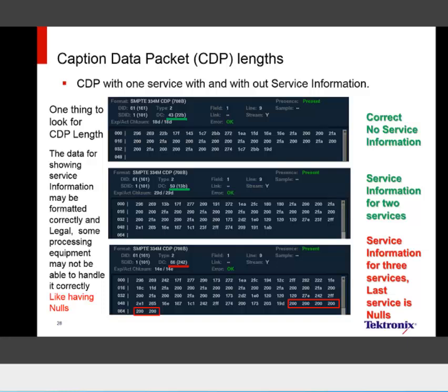This actually made a network start having issues. Whenever a scene change came up, the processing gear would start dropping frames, and the typical frame that it happened to drop happened to be the frame just before a scene change. The frame just before a scene change happened to have the toggle and clear commands. So that meant that the captions never got removed off of the screen from the previous scene.